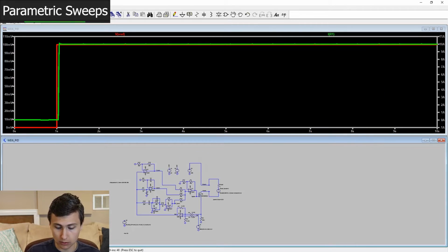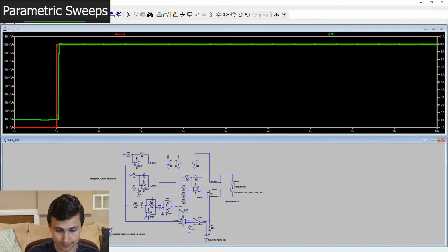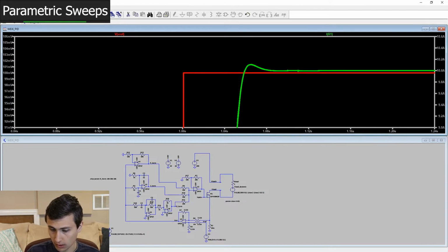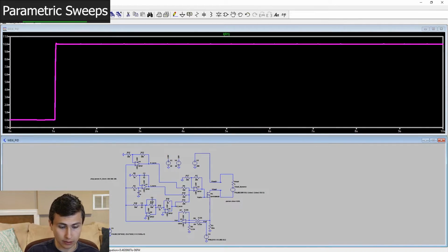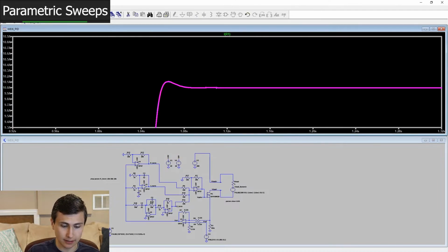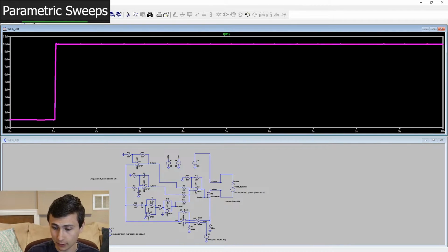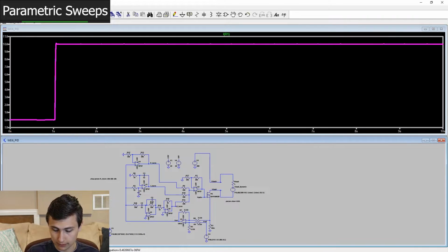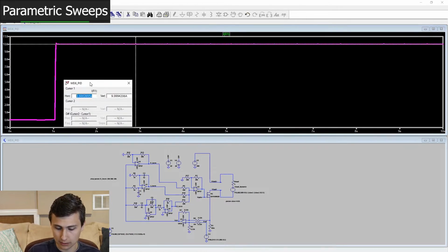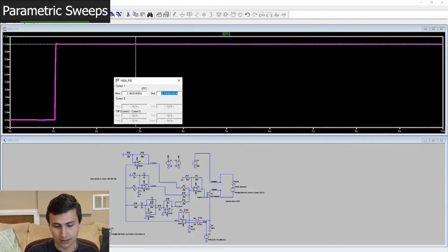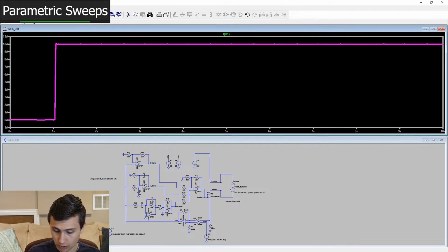Let's view the transient response. Look at that. That's a pretty small overshoot and settles pretty quickly. I like that quite a lot. Let's look at our current. Yes indeed. Settles out at 10 amps with an incredibly high degree of accuracy. What are we at? We are at 9.9994 amps. Here, let me get that pulled over here. Look at that. Quite good.